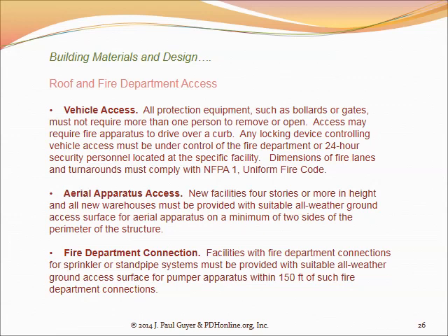And this is necessary in buildings over some certain size, or height rather, because the pressure of the water in the street isn't adequate to get it to the top of any high-rise or even mid-rise building. You have to supplement that pressure, increase the pressure using the pump or pumps in the pumper truck.